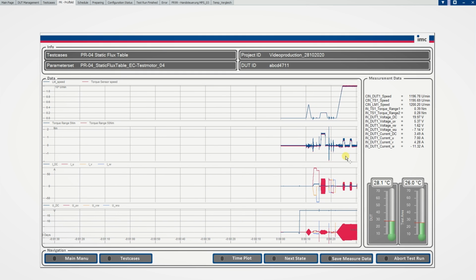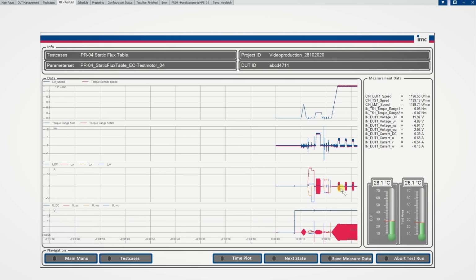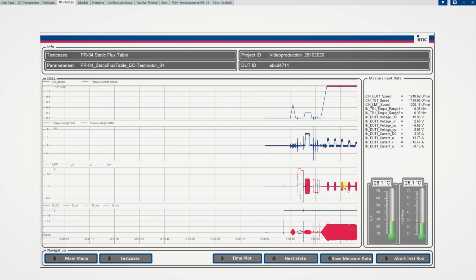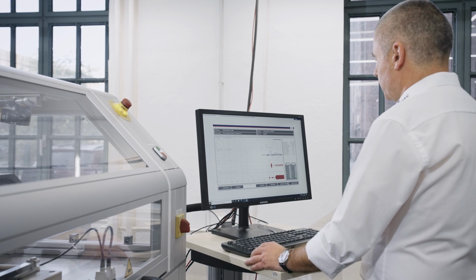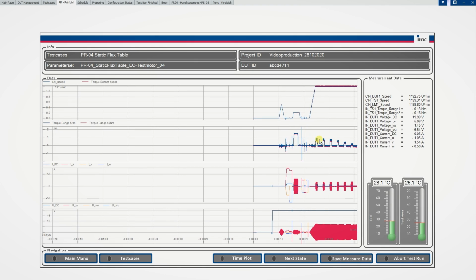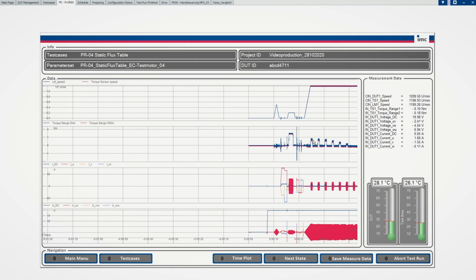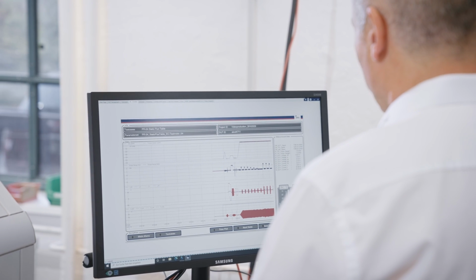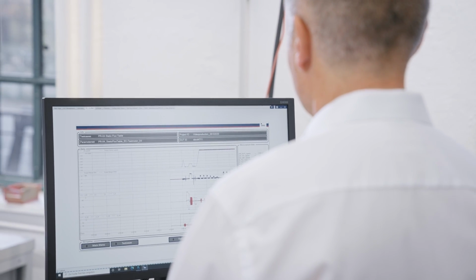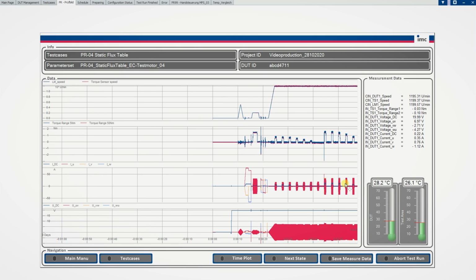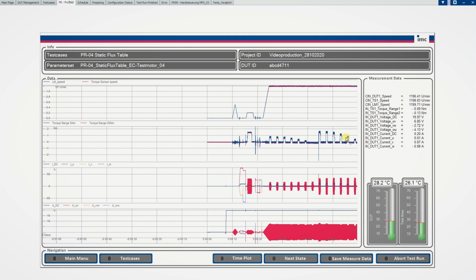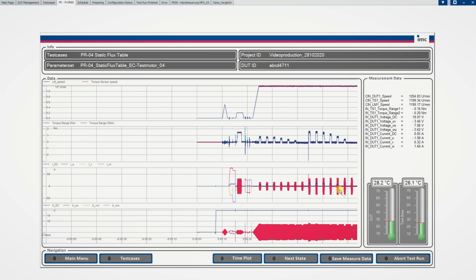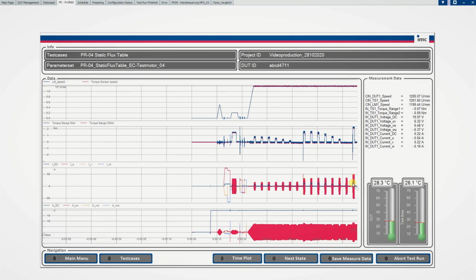We are in line 3, we see the current. This is the first low current range, which goes now over 7 points. And you can see that the torque range is going down while the D current is rising. After these 7 points are done, we go to the next current section, which also goes over 7 points. You see also the torque selection here going down from high to low. And this goes direct to the third section, fourth section and fifth section.